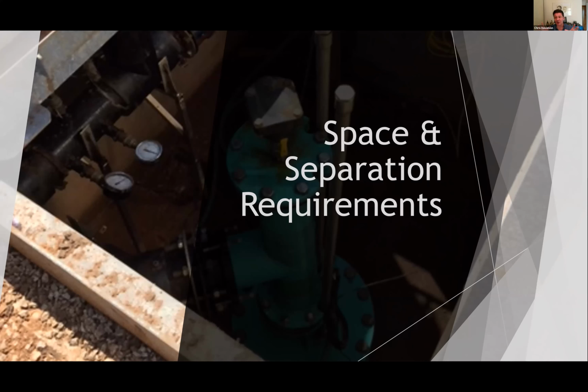I did mention earlier on that open loop requires less space. What I mean by that is the finished well is very small. This is a manhole here you can hopefully just about see in the background with a wellhead in it. An open loop system in its simplistic form would require two of these 100 metres apart, and you've got a functioning system. On the other side, I mentioned systems with 35 metre spacing.